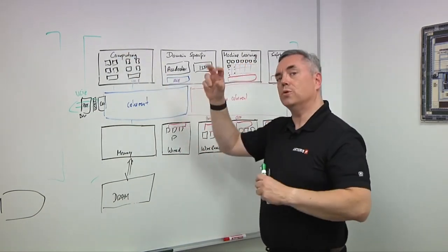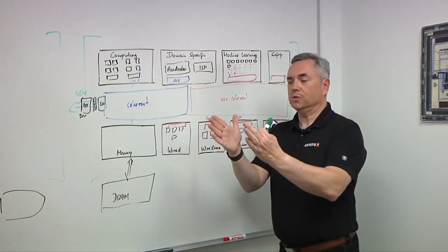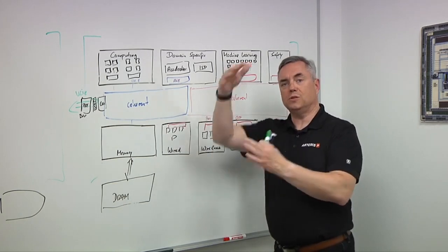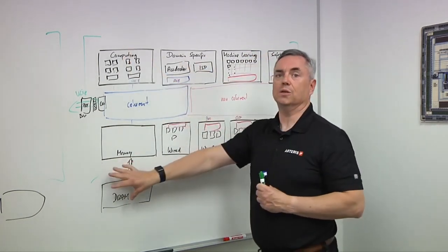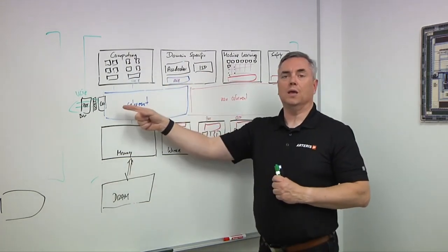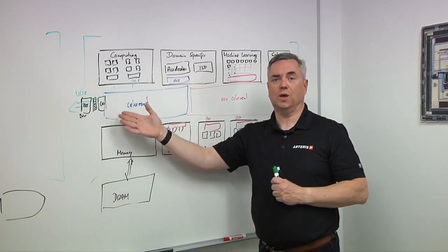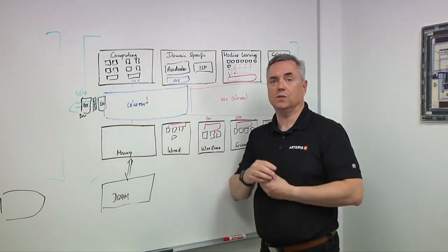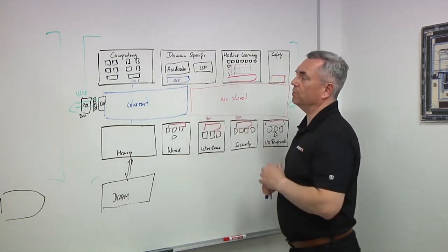Now the poor NOC, to claim a little bit of misery here, has to basically fit into the bits between the floor plan blocks of those items here, right? So now it becomes a question, how long are my wire delays? How many pipeline stages do I have to insert? Those are things which we consider early on in the NOC development process.